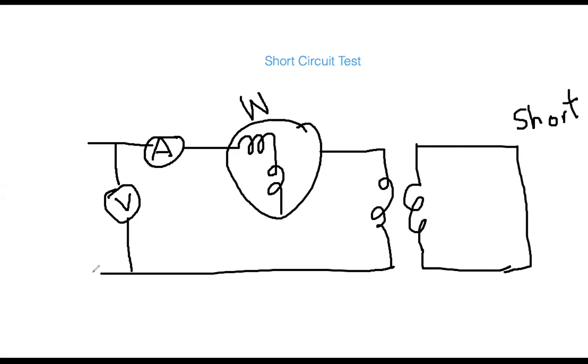So everybody asks, what is the experiment? What is the test? You are applying the voltage at the beginning, and then the current is flowing. You are conducting your test on the primary side. This is the secondary side. Secondary side is short means this side is the LV, low voltage side. This side is the high voltage side.